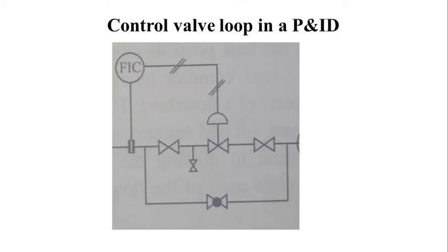The valve which is in parallel with the control valve is the globe valve. Normally, the globe valve will remain shut. All the flow regulation will be through the control valve opening, and quite naturally, the other two gate valves are only for isolating the control valve and sending it for maintenance. During maintenance only, the globe valve will be used for regulation. So the sizing of the globe valve and the control valve will be very similar.